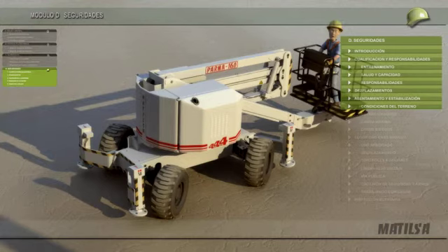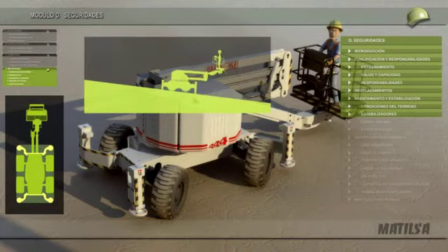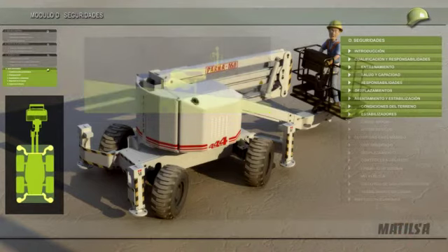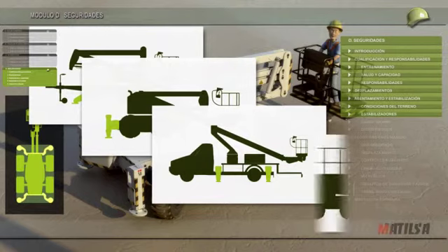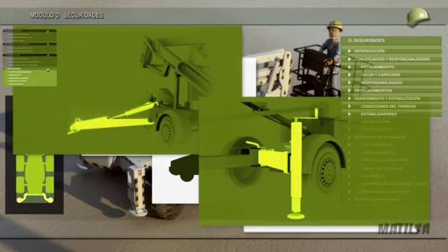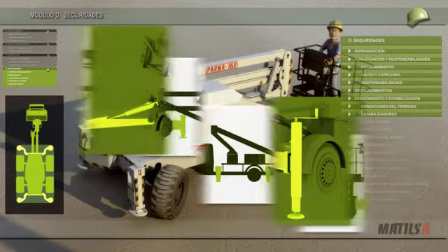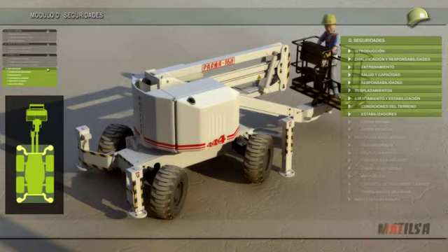The stabilizers are just auxiliary supports that help to give more stability to the machine and to allow leveling when the machine is off balance due to the nature of the ground. It is very common to see them on different kinds of platforms. Trailer-mounted machines, self-propelled with tyres, or crawler type. They may be flapped, telescopic, manual or automatic, depending on the weight of the machine. Its geometry, sideways transporting and the load in the basket will vary according to the supporting surface. It is recommended that all the machines for outdoor work have them as a safety feature for when their use is necessary.